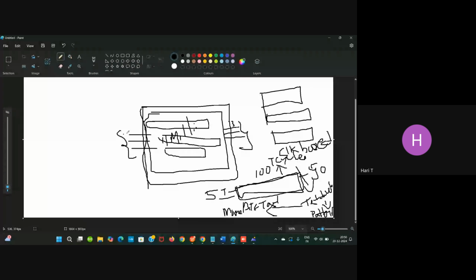And in another way, if you could accommodate 3 pins on either ends, the compression ratio will be 3x. It tends to low number of test cycles and less test data volume, and hence less tester time.